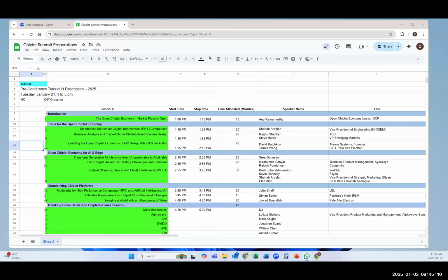There is definitely with hybrid bonding, effectively, you can put your PHY, if you want to, in inverted commas, anywhere on the die, right? It's no longer an edge issue. And if you look at the other standard like UCIe 3D, which is obviously from Intel, they have expanded on that. So I think that when you get to sub 10 micron pitch, wiring stops being your problem.